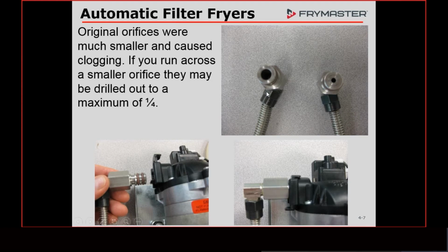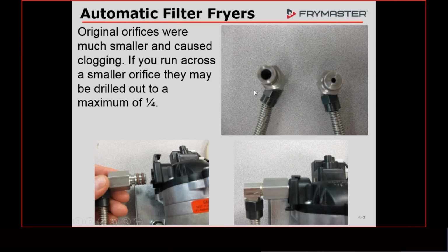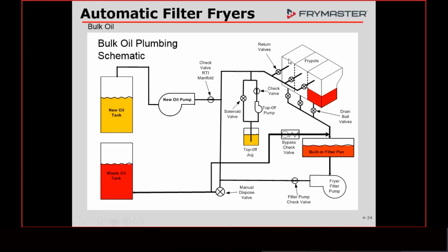But the fact of how this tells whether or not that jib is empty, stuff like this still comes up. Again, if you have multiple attempts to top off that fry pot and it doesn't make it, it could be any one of these things. Most of the time it is never an ATO board. The pumps last forever. But anyway, most of the time it's not one of those components. It's something very simple. And we'll talk about a couple other things.